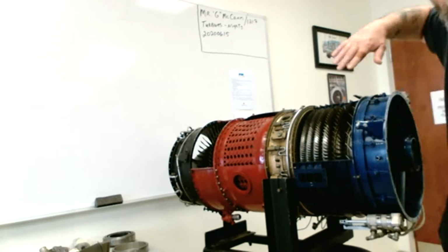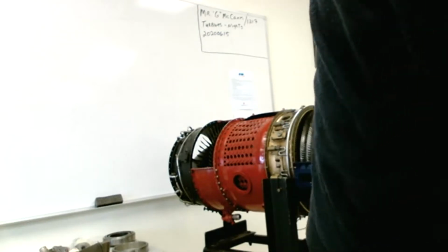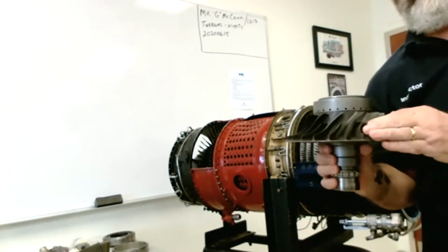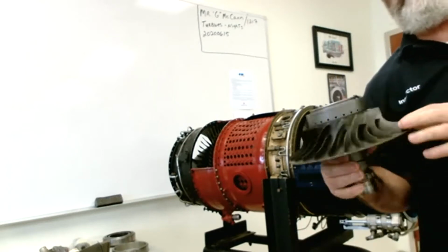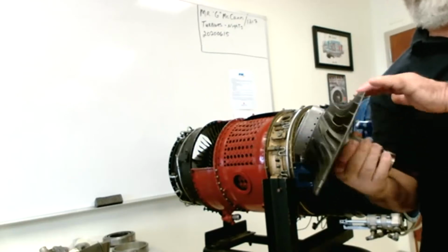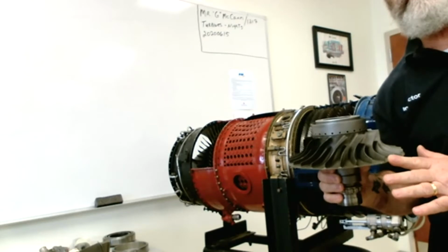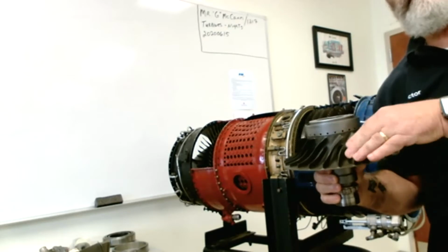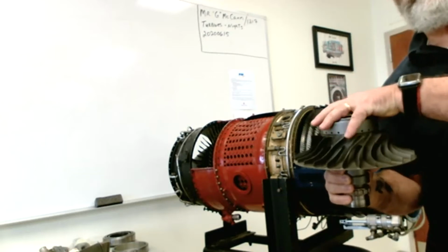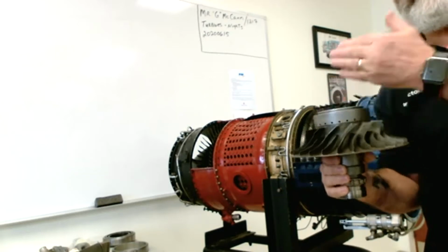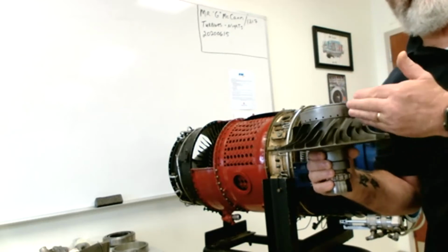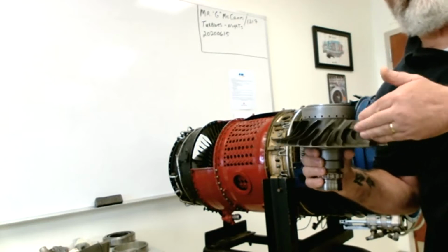Now, there is another kind of compressor. This is an impeller, and this is utilized in a centrifugal compressor. One stage of compression using an impeller or a centrifugal is an impeller and a diffuser, not a rotor and a stator, an impeller and a diffuser. So just kind of keep that on the side. Air is compressed here and accelerates it outwards. That's how the FAA describes that in a question, and that is a fact.